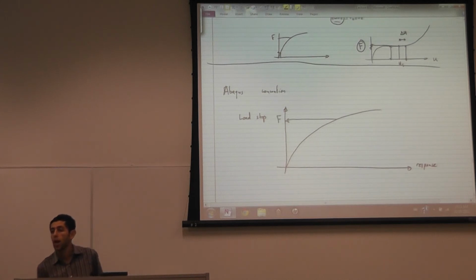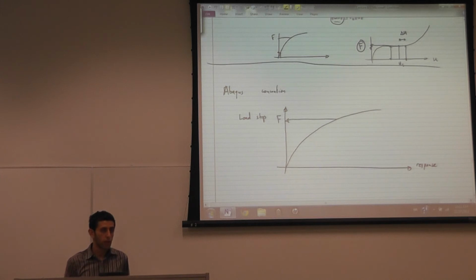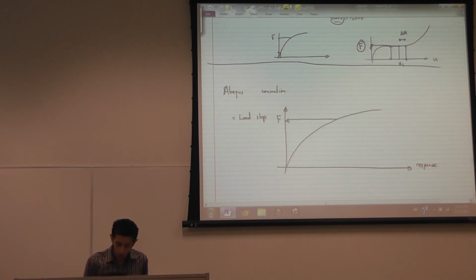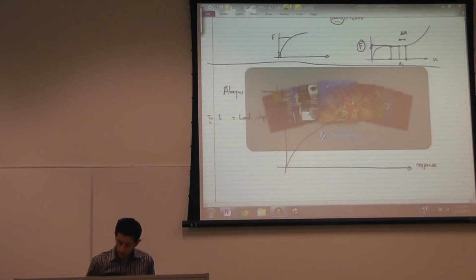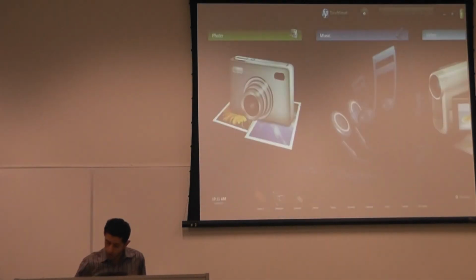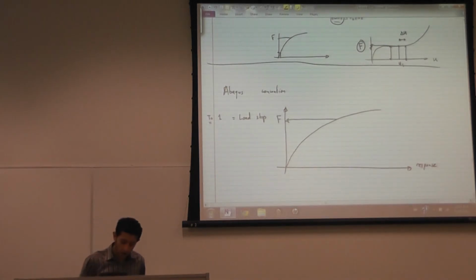So in a load step, you apply 20 or 200 Newton, for example. Usually, the full load step corresponds to a fictitious time if the structure response is not time dependent. Let's say t is equal to 1, or whatever fictitious time you put. This is equivalent to 1 unit of time.